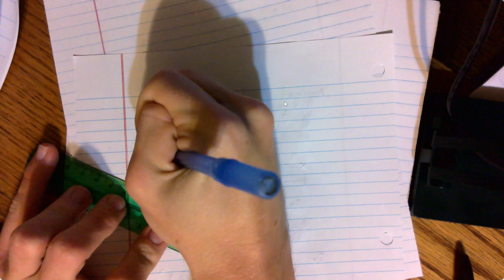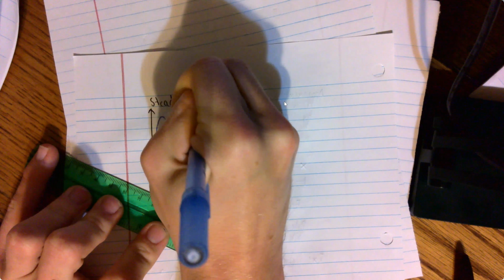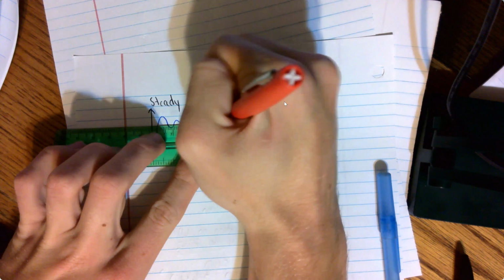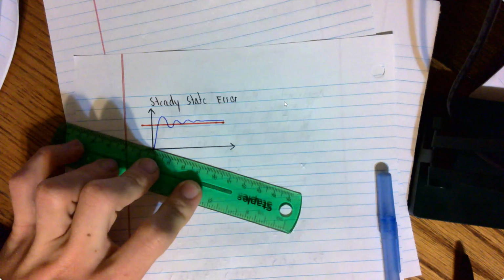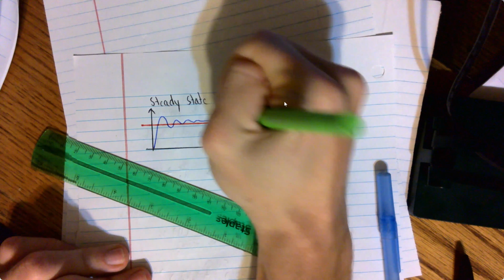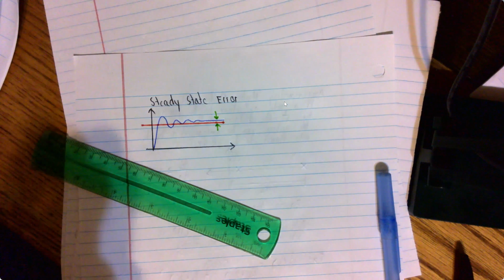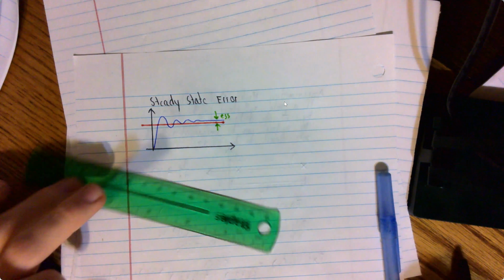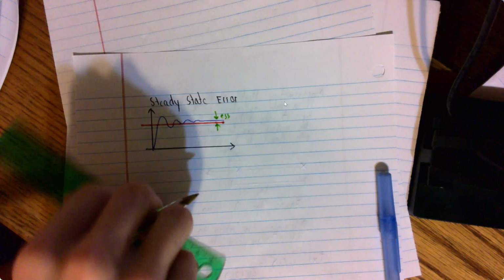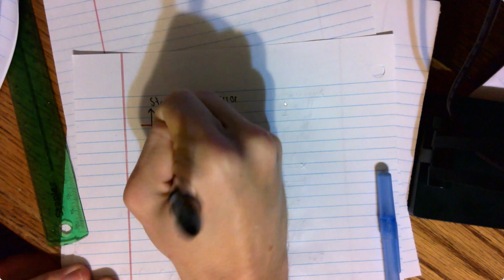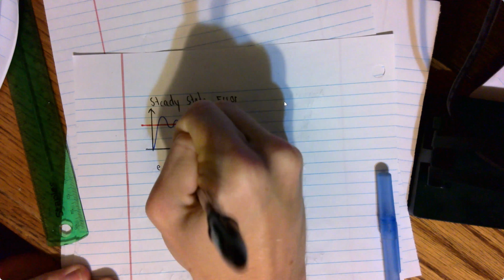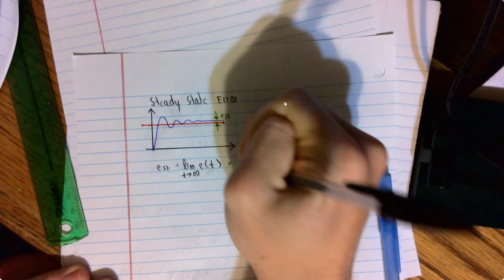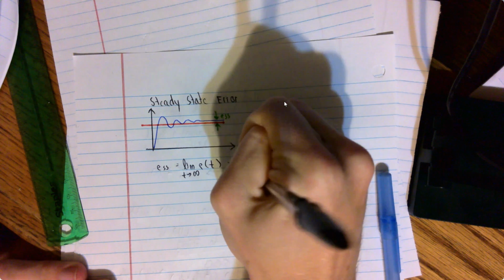So a lot of times when we calculate steady state error, if we have our second order system and it goes to a certain value, say here, but the value that we actually wanted was right here, there's going to be a little difference in the error. So our final value does not match what we want for the final value. This difference between the two is known as the steady state error, because you didn't approach the value you wanted in the end. So steady state error is defined as the limit as t goes to infinity of e(t). And using the final value theorem from the Laplace table, you can write it in this format here.